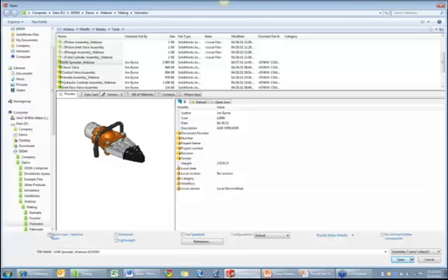Quick View is another option that came up after lightweight. If you check this box, it enables you to select the components that you want to work on before it loads everything. And literally, anything that you don't select does not load. The only issue is that when I suppress components in my assembly, it also suppresses the mates. But when you use Quick View, it doesn't load those components. It's kind of like leaving them suppressed, but the mates are still maintained. So this is also another thing to keep in mind when it comes to mates: if you use Quick View and only load a few of the components, all the mates are still maintained.